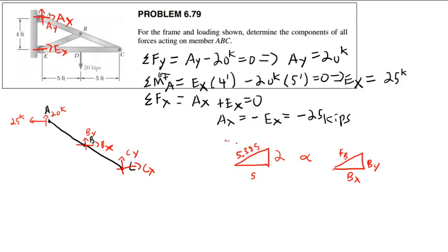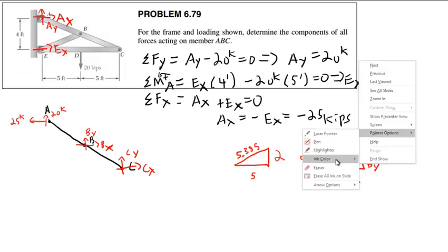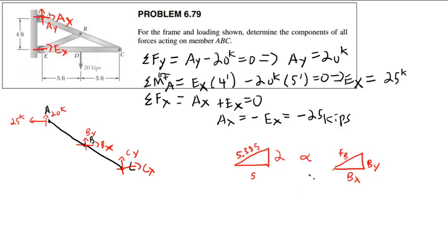So if we were to draw member EDC, we would have to draw the end forces. We could not simply say they reduce to a single axial force, because this member may carry shear and moment. But essentially, what this member gives us is a new equation.